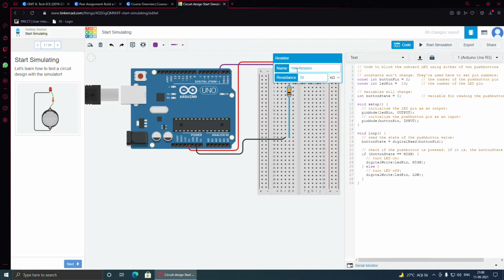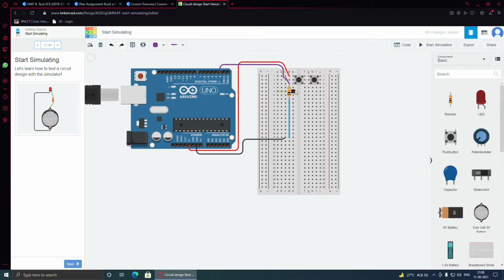And we use a resistor of such a value which will maintain the current flowing through the component close to or equal to its current rating. So according to that, we decide what value of resistor, how much ohm that resistor has to be. So that's the use of a resistor, so that the component isn't damaged through the passing of a high value of current. Okay, so that's the use of a resistor.